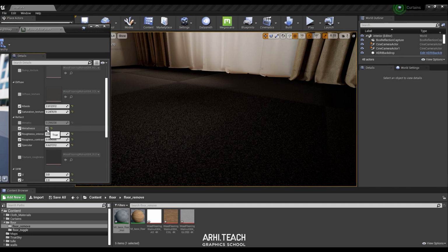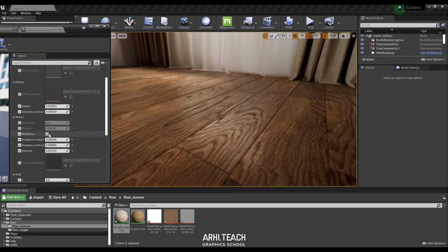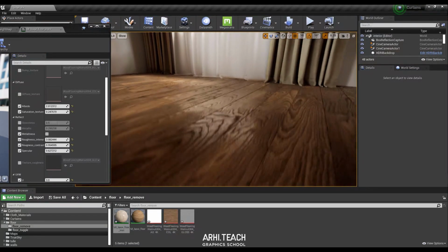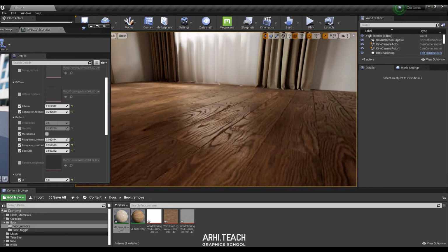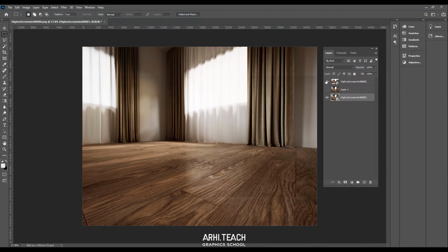Okay, so what's going on here? Look, when we turn on metalness, glossiness disappears. Do you see it? And conversely, turn off metalness and glossiness instantly appears here. And now let's play with these parameters. What do we want to achieve by this? Here we have the usual glossiness. And here we have metalness. Choose the material that suits you best, the parameter that will work for you.